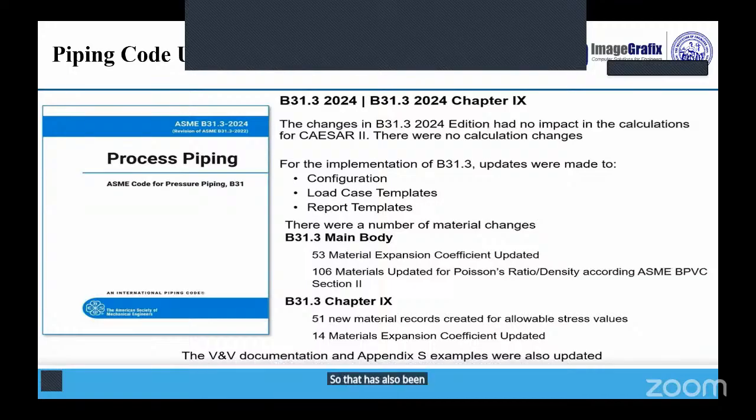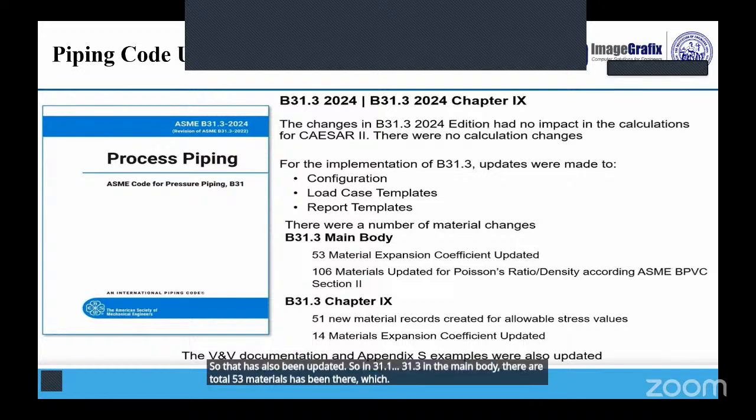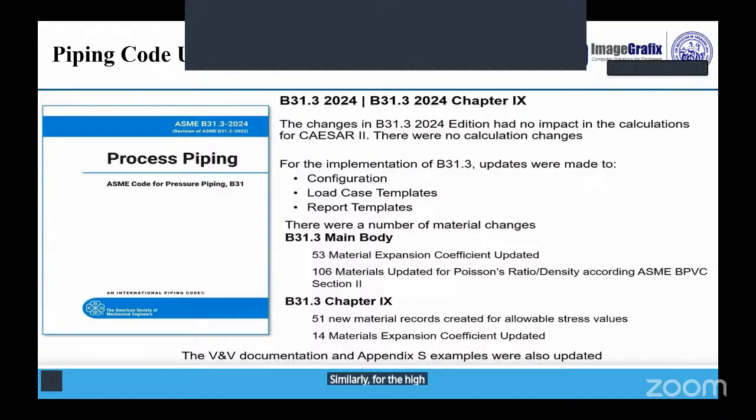In 31.3 main body, a total of 553 materials have been updated for the expansion coefficient, and 106 materials have been updated for the Poisson ratio and the density according to the ASME BPVC Section 2. Similarly, for the high pressure systems, according to Chapter 9, 51 new material records have been created for allowable stress values, and 14 materials have been changed for the expansion coefficient update.